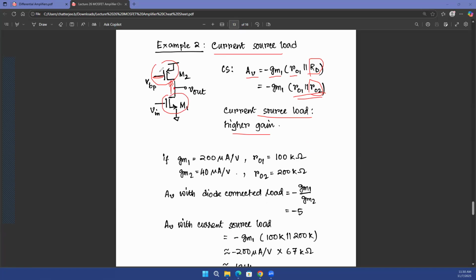So what the upper transistor is doing is that it has a fixed VGS. The gate voltage is fixed, the source voltage is fixed. So if it is in saturation, it's going to generate a fixed output current. It is just going to work as a current source with a fixed current. And that's why this type of load is called current source load, because your gate to source voltage is a DC voltage. There's no concept of AC anymore for the top transistor. So it's working just as a DC current source, and that's it. The gain is provided by the bottom transistor over here.